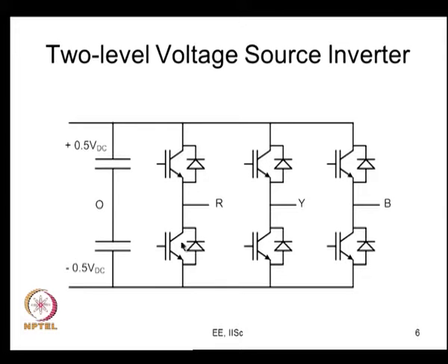So, when this device is to be turned on, what happens? There is voltage across that, and the voltage has to collapse down to 0, and the current has to rise through this particular device. The current starts rising well before the voltage starts falling, and therefore, there is a certain amount of loss here. Which is what we are going to look at today.